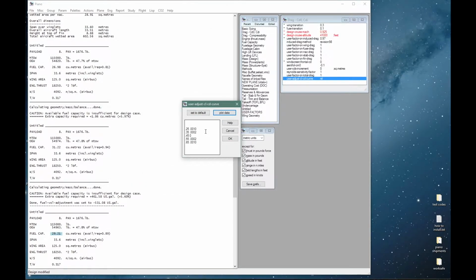So now we're assuming a slightly lower typical design CL, bearing in mind wing loadings will be lower. Also, in the case of a business jet, we don't want to tune the design too much for a single cruise CL and Mach number, as we might do for a 787 or an A350. That is because we now have to balance an optimum with a desire to retain adequate performance at higher speeds like Mach 0.9.